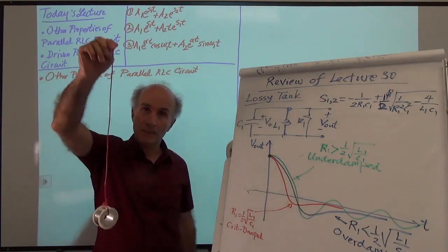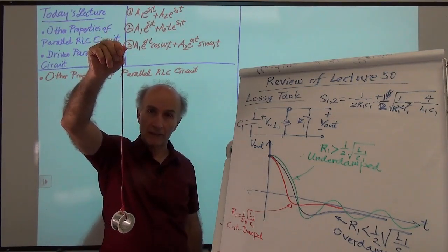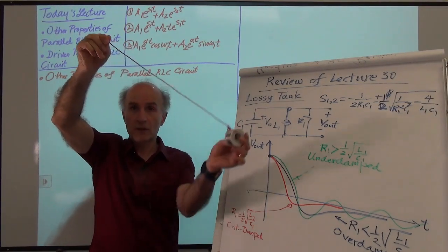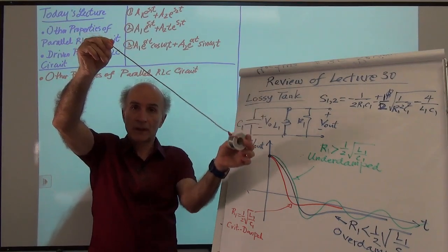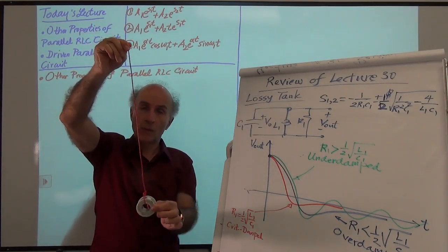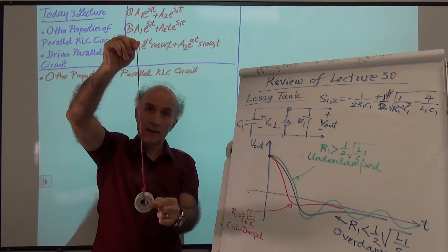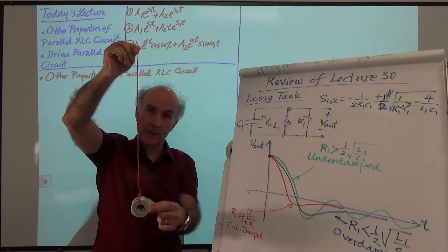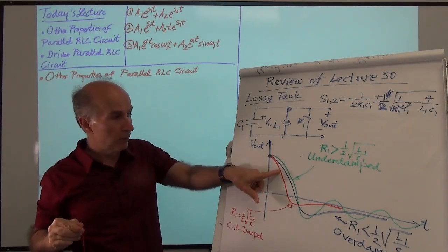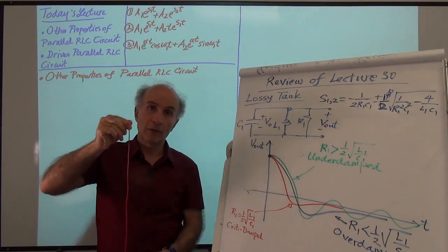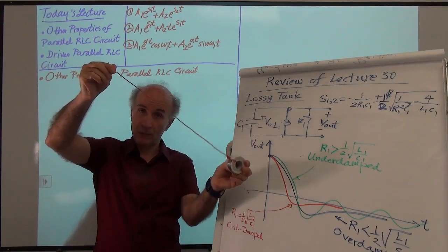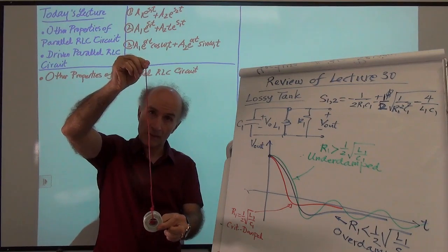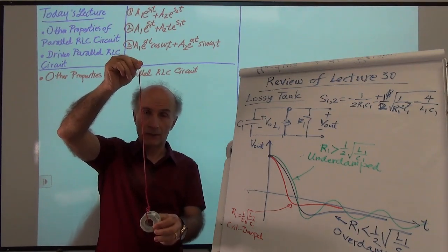How could I make this pendulum behave like that, approximately speaking? So what I would like to do is for this pendulum to just come down like this, go past the vertical position a little bit, and then just gradually come back to vertical position, right? That's what it means to have this blue waveform. The blue waveform wants to reach its final value, which would be here, but it has a bit of undershoot and then comes back slowly to its final value.